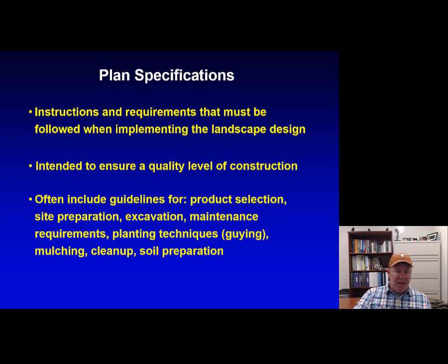And then, last but not least, but probably one of the most important things I think when it comes to irrigation and landscaping, is that we don't necessarily take the time to do good soil preparation. Using the correct soil amendments, using peat moss, soil conditioner, and things like that, and actually prepping the beds and prepping the soil will actually help us as irrigation and landscape contractors.